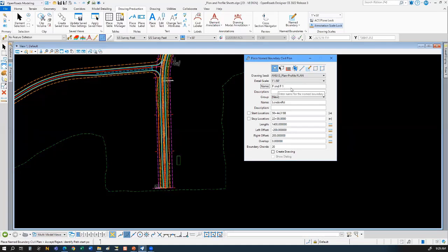But there are 2 tips, I guess, here that you want to make sure you do. One is you want to make sure you always put, in my case, I always put the number 1 in the front, because what this will do is it's going to lay out shapes, and you don't want your first shape to be just called, sorry, I changed it because I didn't tab. Oh, I got 3 tips actually. P and P1, and then hit the tab key. When you're done typing in, hit the tab key. That will move you to the next data field, and it will lock in that value there. Okay, see, now it doesn't change on me. Okay, so that was tip 1.